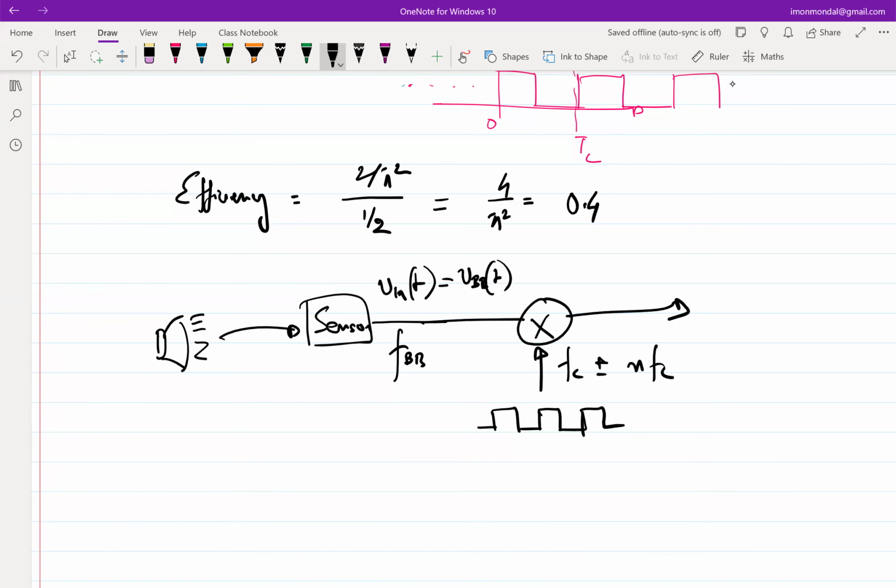Now I have to transmit it, right? Ultimately, the whole goal is to transmit it over a wireless channel, right? If that was not necessary from the start, we could have as well not done any frequency translation. A simple wire would have been enough. So we need to send it across free space. So for that, we need an antenna. This is not an antenna design course. We'll assume the antenna exists. Size of the antenna will be of the order of 1 over FC, right? So because FC is high, size of the antenna will be manageable.